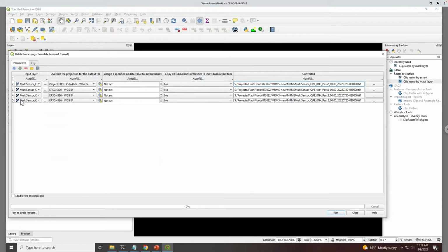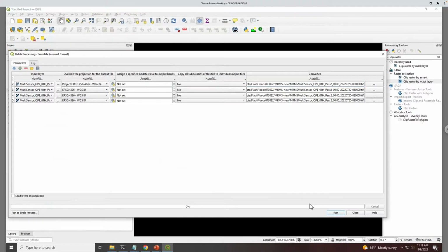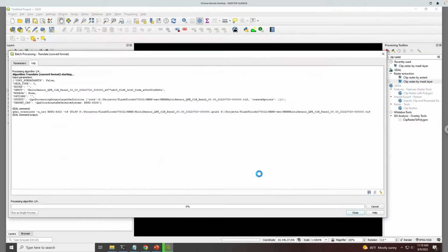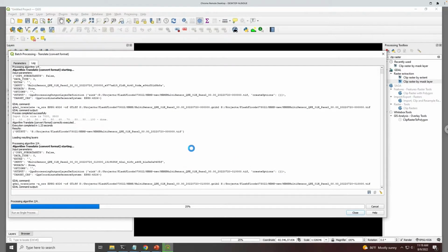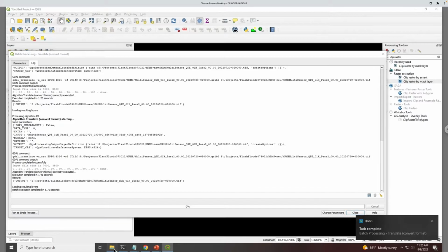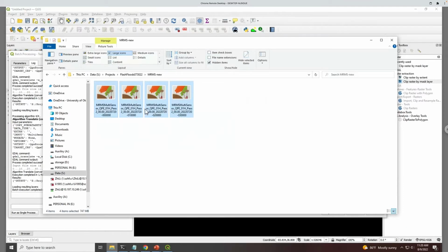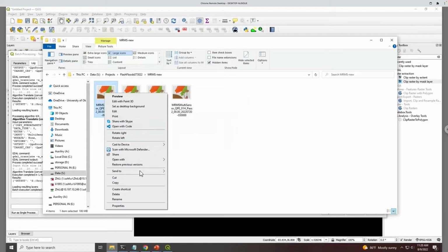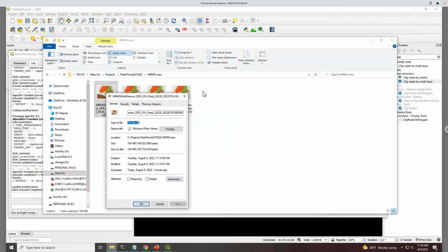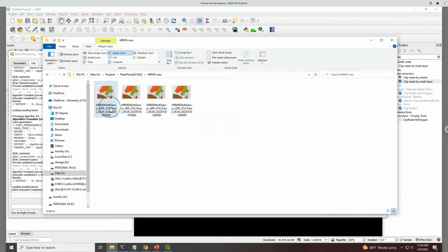So basically, as long as you have as much geospatial rainfall data as possible, then you can run it. Click run. You don't have to clip into the basin format in this way because the software itself can handle this for you. So after this, you can see we have 4 generated GeoTIFF files from this data. This is a format that the EF5 or CREST program can read.